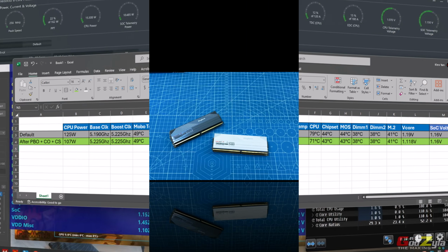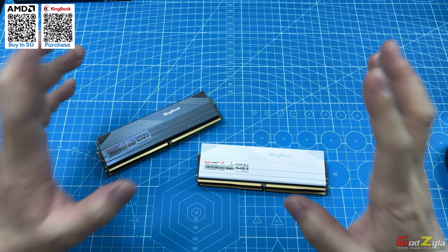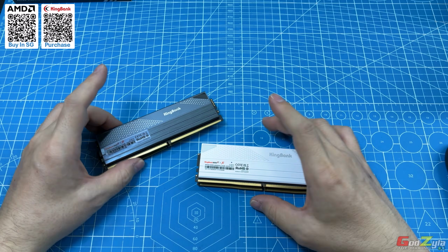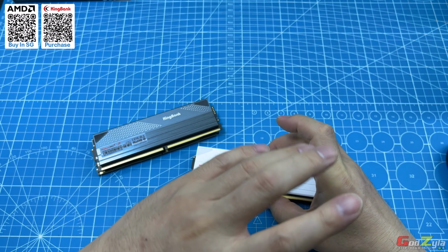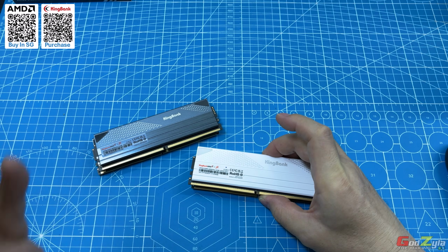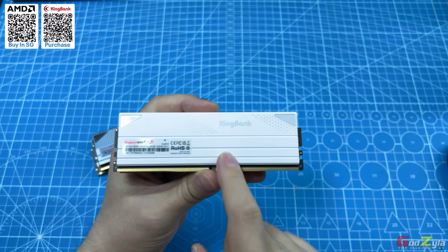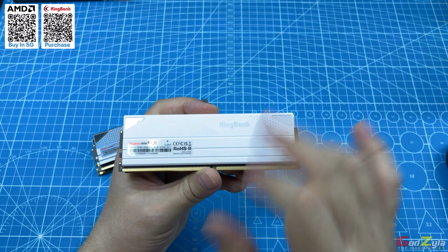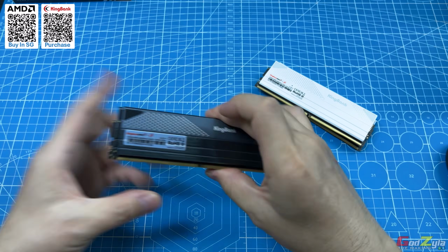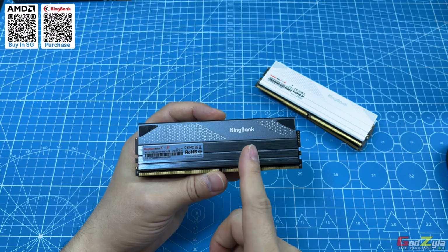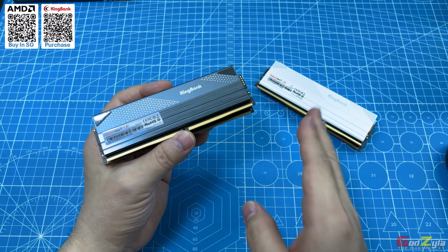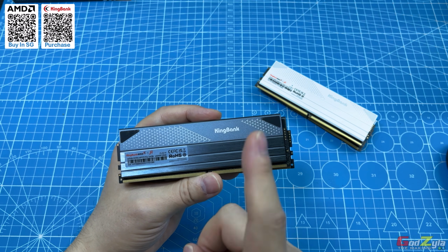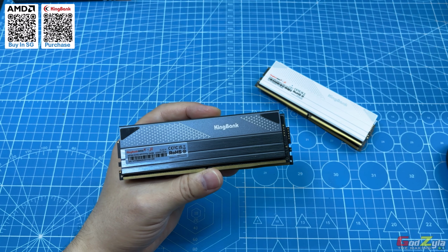23,126. This is the point you will have to take note of when you're using high bus speed RAMs. In fact, the first run that you saw in the content itself is making use of this CL28 48GB kit running on bus speed 6000. I removed this off. I will plug this in later to show you, these are similar capacity, which is a 48GB kit, running a cache latency of CL32, but the bus speed on 6800.